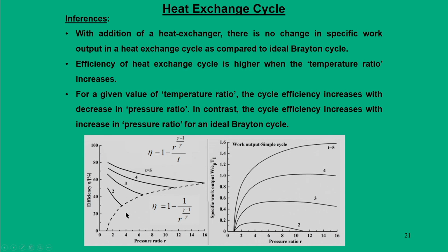But the interesting fact is that for a simple cycle, with increase in the pressure ratio, the efficiency goes up. But for a heat exchange cycle, with increase in the pressure ratio at a given temperature ratio, the efficiency falls. This is quite an interesting factor.